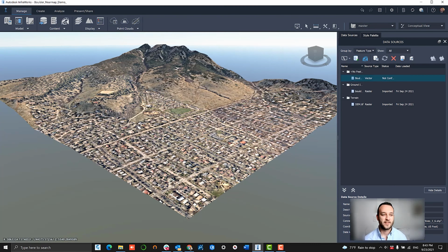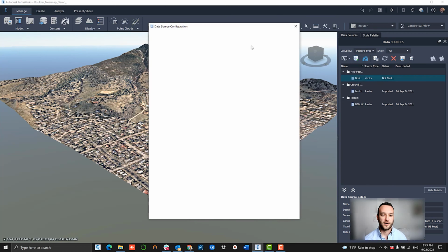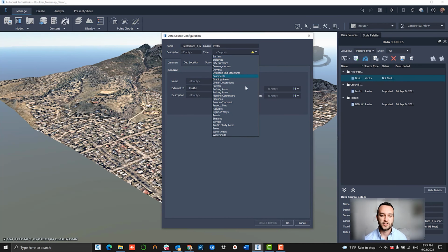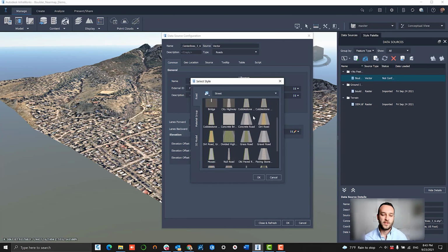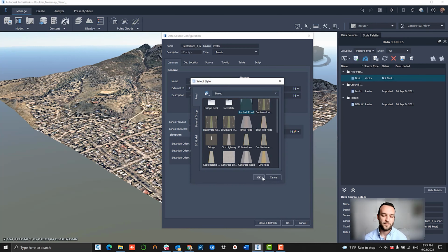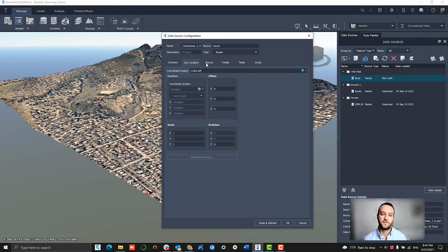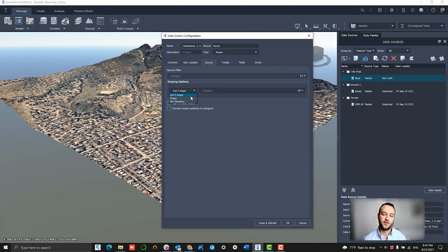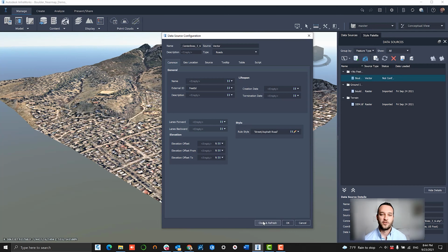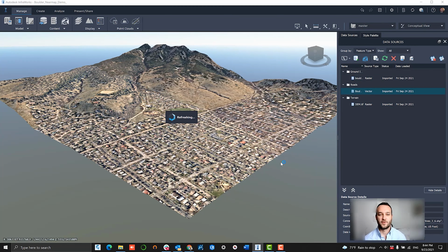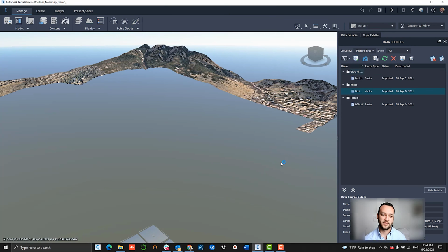So we load this content up by going to our directory here and loading a shapefile that identifies those road center lines. We want to make sure we load that content as the road InfraWorks layer, and then we want to select a style that fits with the environment, so that we already know what that road is going to look like. Here I just have a basic asphalt layer. And then we're going to drape that onto our existing terrain. Since these are existing roads, we want it to match the profile of the ground data that we've already loaded.